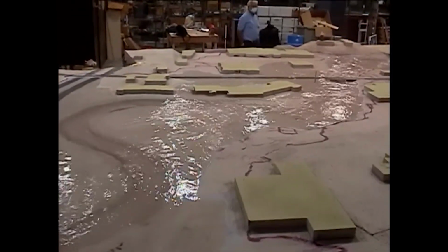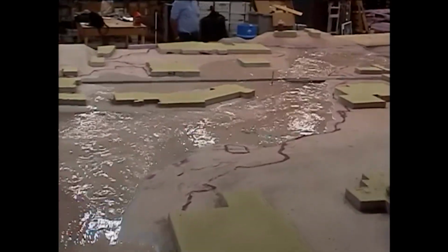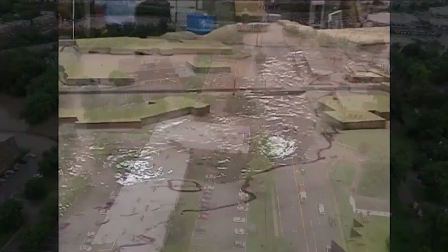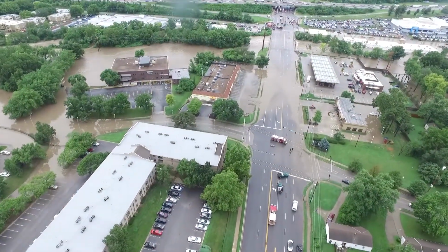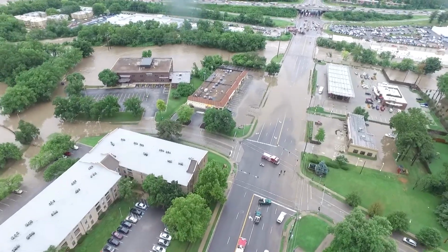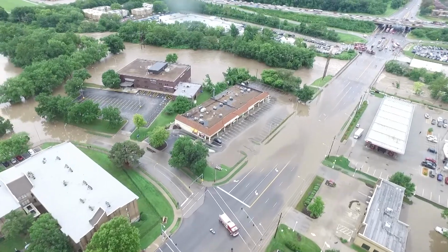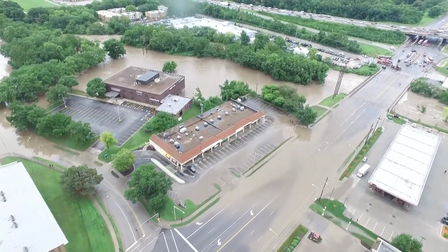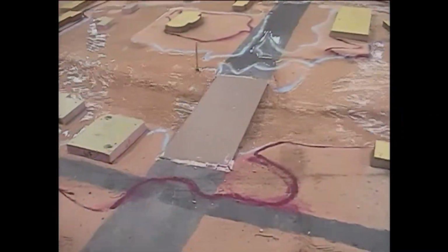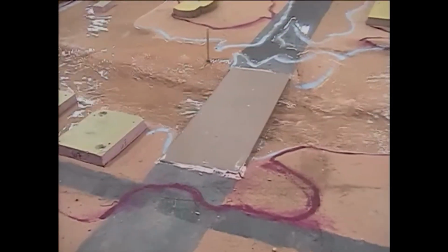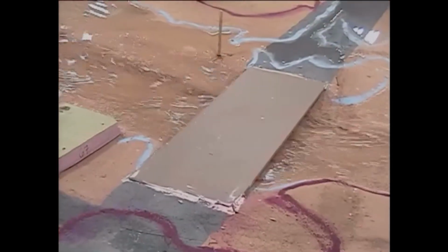We were also able to explain a convenience store located right next to the creek that had been more recently built than the rest of the neighborhood. While that store didn't flood, it showed the effects of its building pad and how it diverted flow around the building and actually sent water in directions that people weren't necessarily expecting.